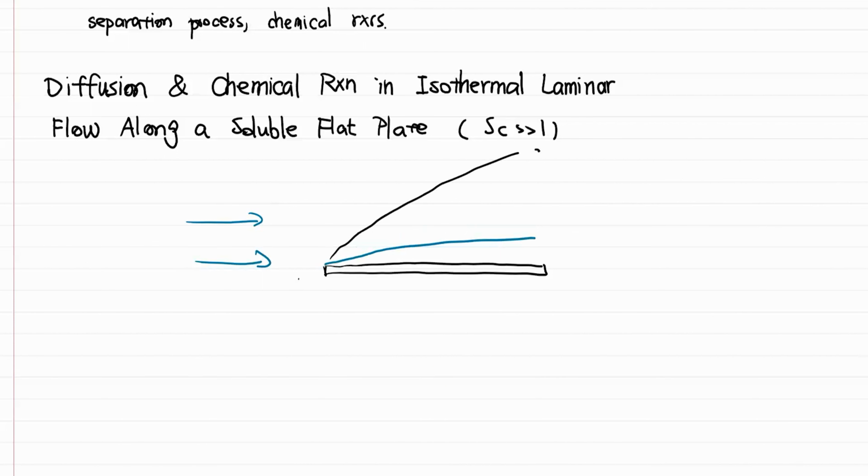So this up here would be our velocity boundary layer. What's down here would be our diffusional boundary layer. So we would expect a velocity distribution that looks like this, right? Outside the boundary layer, the velocity would all be the same as the potential flow, but inside we have a curve-like shape.